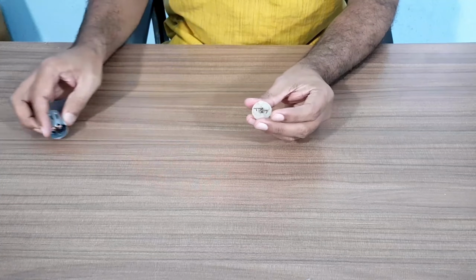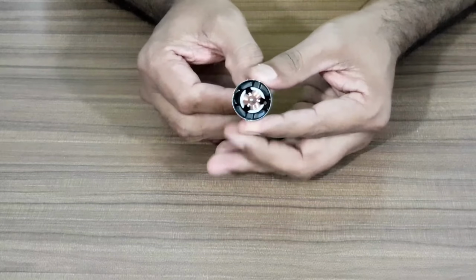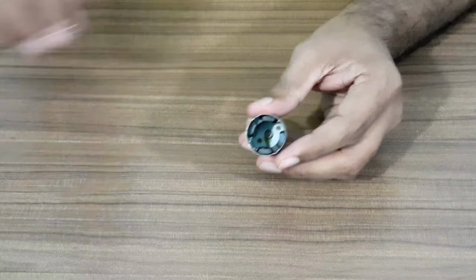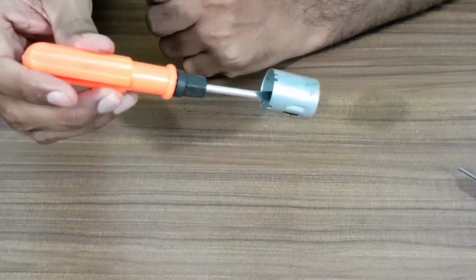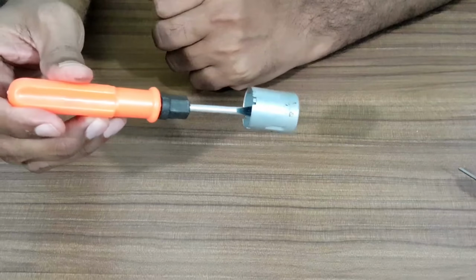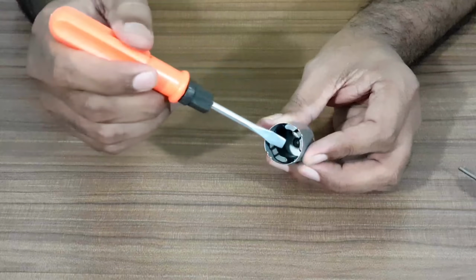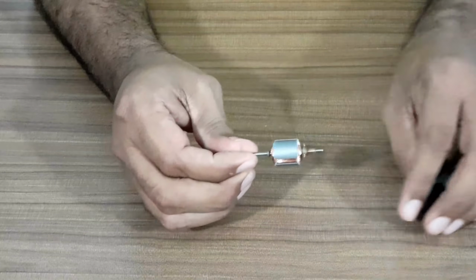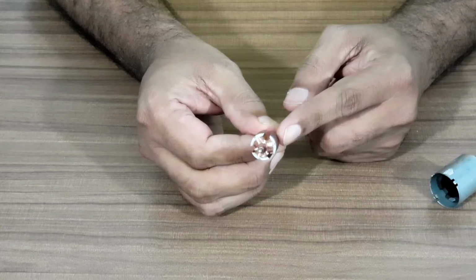So here you can see the inner structure. I will keep it aside. This is the connector, and see here what is inside. First of all, see this thing. There are magnets inside. If I hold it here, there is a strong magnet. To be a dynamo, it is very important that you have a very strong magnetic field. After this, if you see it clearly, it's a copper winding,